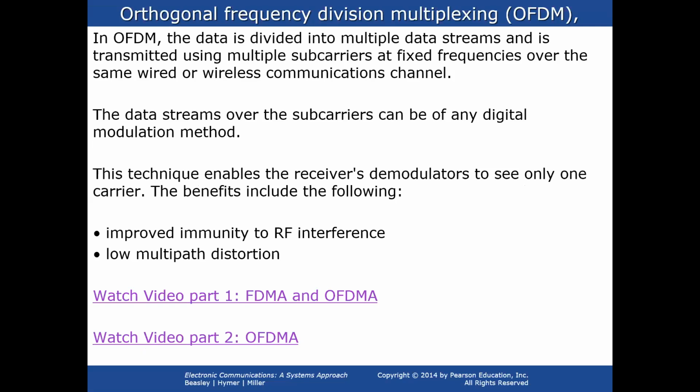Hello friends. Welcome back to the world of 4G. Today we will discuss uplink and downlink data transmission in the network. As discussed earlier, data is transmitted in OFDMA over parallel subcarriers of 15 kHz. The subcarriers are further divided on the time axis as blocks of one symbol duration, or 66.7 microseconds. This basic unit is known as a resource element. Each resource element carries one symbol.